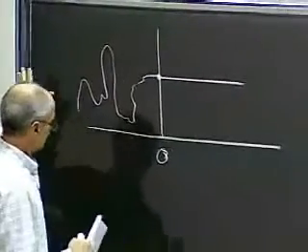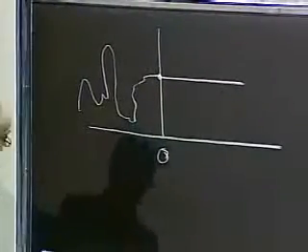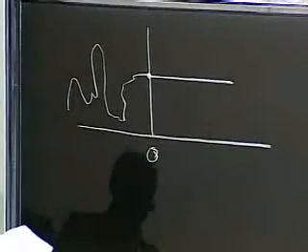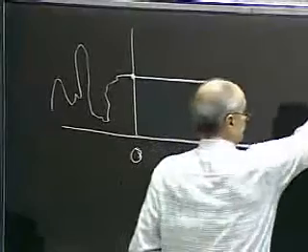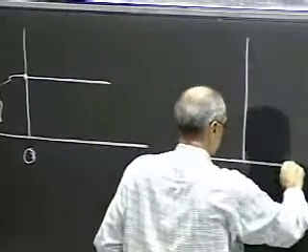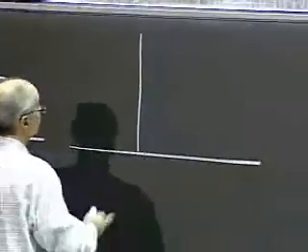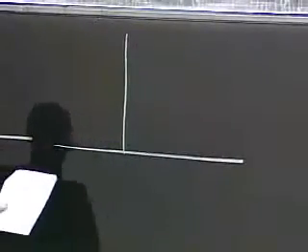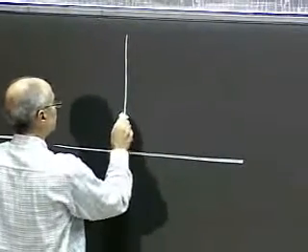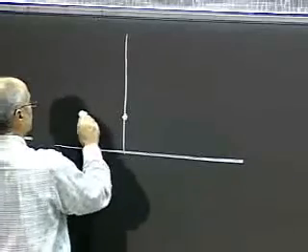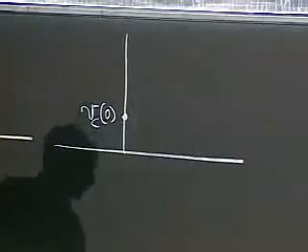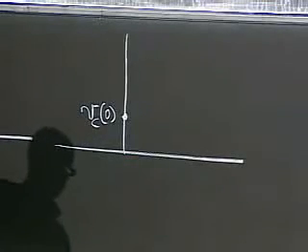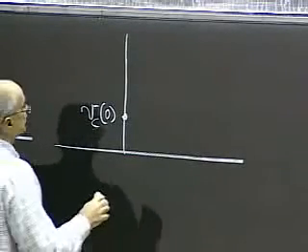And so the history of Vi really doesn't matter. The response following that equation that we have there will depend on the initial value, which is Vc of 0 here, the voltage on the capacitor at that time.